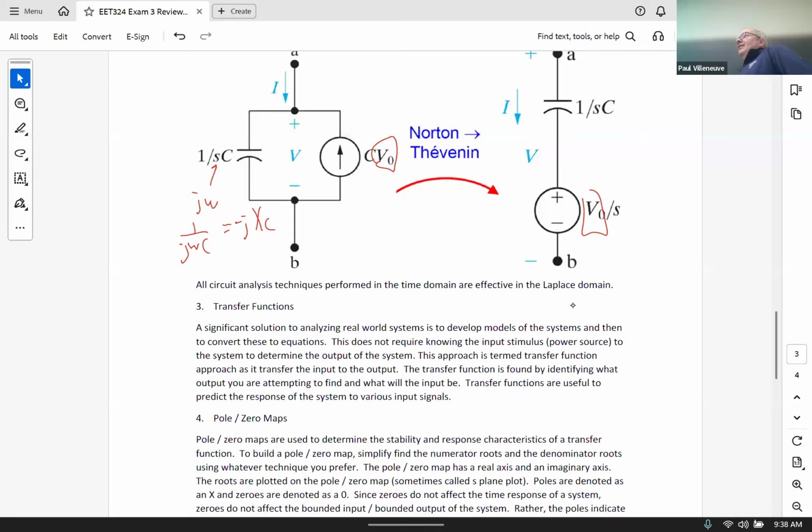Okay. Because the whole thing about AC circuit analysis, and the reason we can simplify it a lot, is that if you had resistors, inductors, and capacitors, you'd have to write differential equations for AC circuits. It's the same thing, isn't it? But Laplace means we can write everything as multiplication, but we have to be in the Laplace domain.